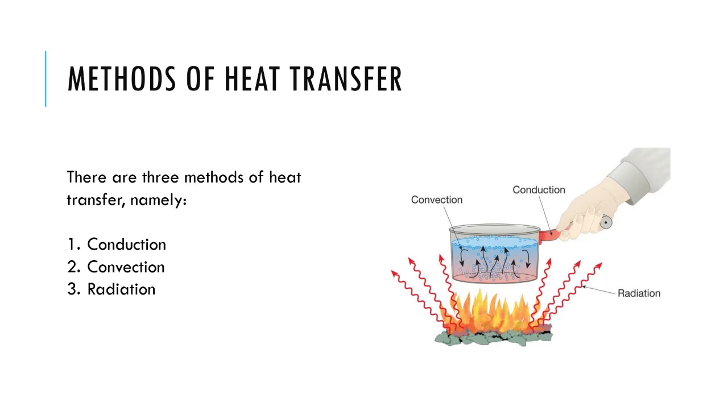Next is convection, and in this particular case we will have natural convection. So one might ask, how does it take place? In this case, convection will happen as the bottom of the pan gets heated. It will heat up the bottom water molecules, and as they get heated, they will expand and get excited, and hot things generally rise. Also, they will experience a buoyant force due to decrease in density, and they will rise up. And cold water will come to take its place, which will also heat up, and therefore a convection current would be formed.